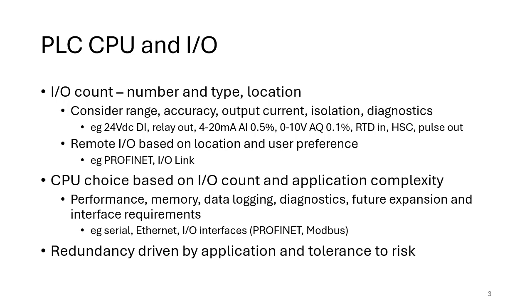So based on what the location is and also possibly the user preference and also commercial considerations such as cost and effectiveness, you might consider Profinet, which is an Ethernet based remote I/O connection. You might consider IO-Link. IO-Link might be useful on a machine basis, particularly because you can have IO-Link interfaces which can be IP67 protected, so ideal for machine mounting without an enclosure. And there might be other considerations as well based on what equipment you're interfacing to and what available communications they have.